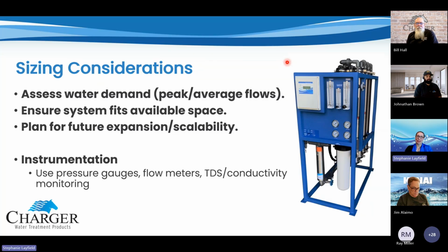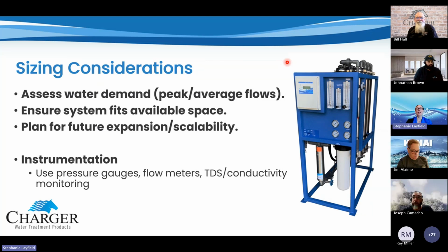We also make sure that the system fits in the space that we have. Some of these get really big. Make sure it fits through the door, because that's not fun when you get there. And with any system, any mineral tank too, measure the door and make sure you can get through. And plan for the future. A lot of these commercial applications, as businesses grow or change, having these in a modular configuration with our pre-treatment and post-treatment is really nice, because we can scale it up as we need.